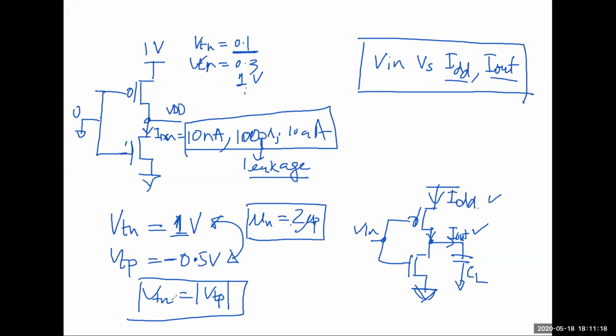In an interview, always remember, maybe you can solve it and come up with some very fancy curve. I'm not expecting you to give me a very fancy curve on the basis of the equation. I want all of you to think logically first, without keeping equations in mind, just with the help of some voltages: when PMOS is going to be on, when NMOS is going to be on, in which region, what is going to be the curve, and accordingly draw a rough diagram.